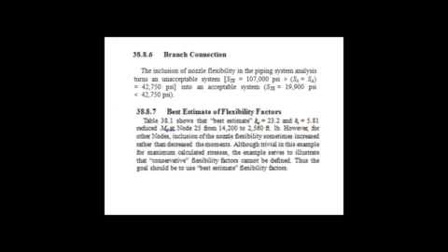So let's go see what conclusion Ev Rodabaugh drew for this system. When he analyzed this, according to Section 3, it was unacceptable. The stress was 107,000 psi without flexibilities, and it was easily acceptable. The stress was 19,900 psi when he added flexibilities. Now, Rodabaugh also stated something that was interesting, I think, about flexibilities, because he states that conservative flexibilities cannot be defined. Thus, the goal should be to get best estimate flexibility factors.